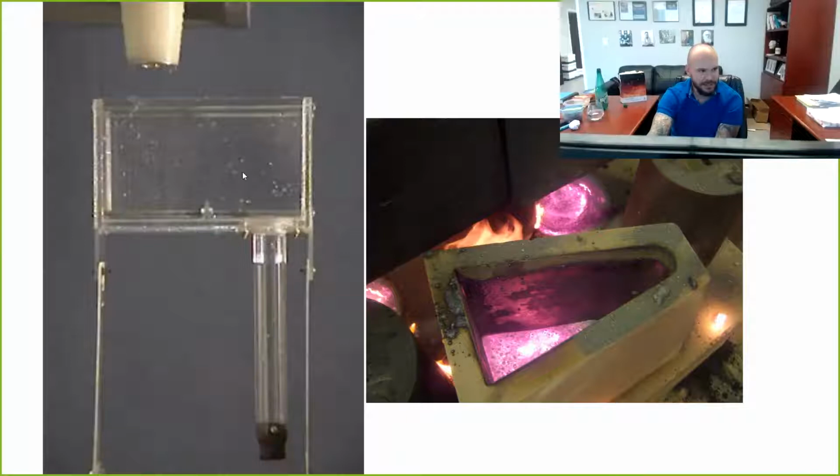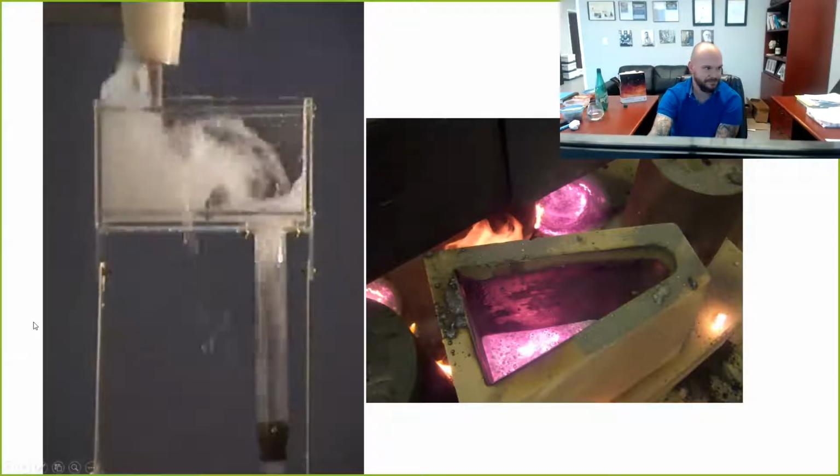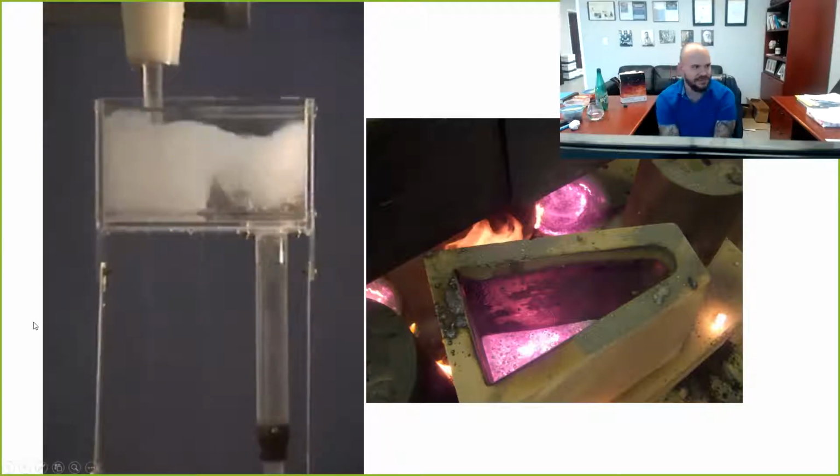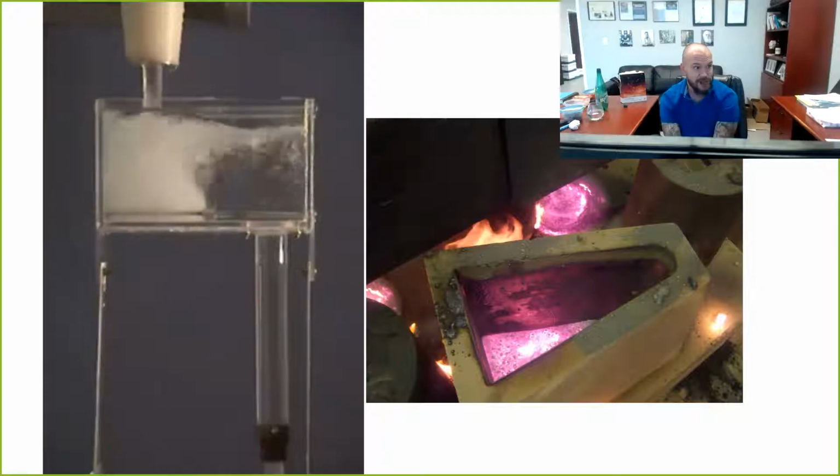Then the velocity will be determined by the height of the metal in the basin. The idea is let's prevent an aspiration mechanism, and let's provide an opportunity for detrainment of ladle slags, those kinds of things that might enter the system. So let's take a look at how that works. You can see in the first few seconds of filling that there's tons of air, but now when the system is primed, you can see that no air or almost no air is entering the system.